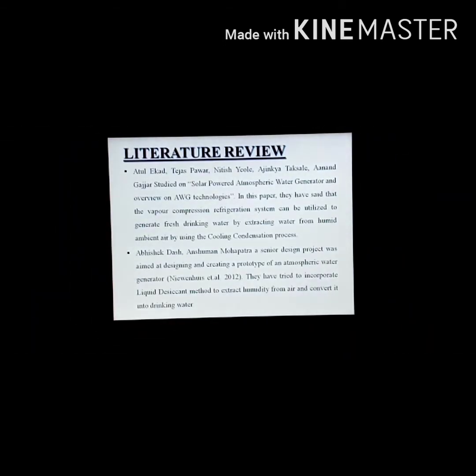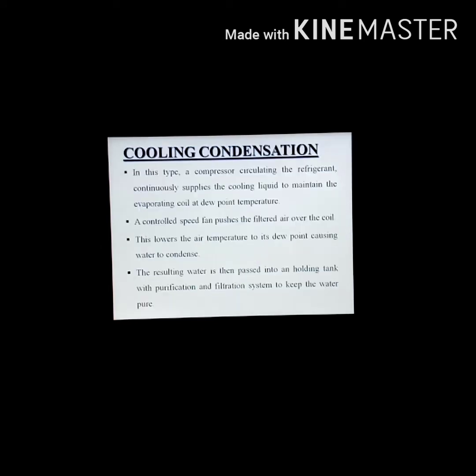This is the literature review which I referred. There are two methods, the first being the cooling condensation method. In this type, a compressor circulating the refrigerant continuously supplies the cooling liquid to maintain the evaporating coil at dew point temperature. Dew point temperature is the temperature at which water vapor will condense to form liquid water.